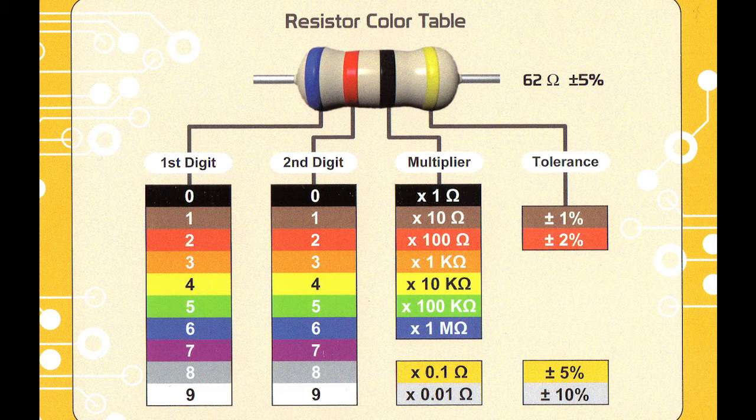So you probably noticed those cute little colored bands on the side of the resistor. Those are actually telling you what value resistance this resistor is supposed to be. Let's go over that. Okay, so we need to find the end of the resistor where the colored bands are packed tighter together, and the last band that we're concerned with is almost always silver or gold. So we'll look for that as well.